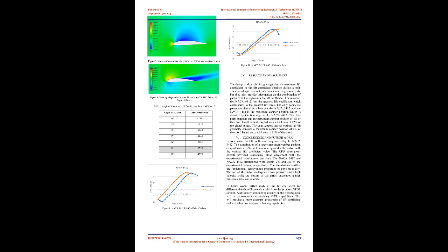B. Physical domain and boundary conditions. This study used an enclosed volume containing a semicircle and a rectangular shape. I divided the volume into 4 quadrants. This step was useful for meshing a C-shaped mesh along the left half of the enclosed volume. The outer edge along the semicircle is the inlet. The outer edge along the right half of the rectangle will be the pressure outlet.